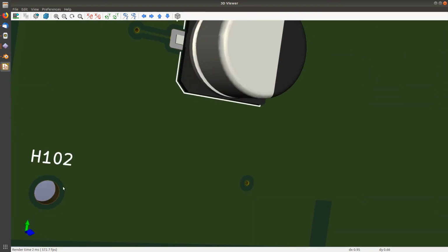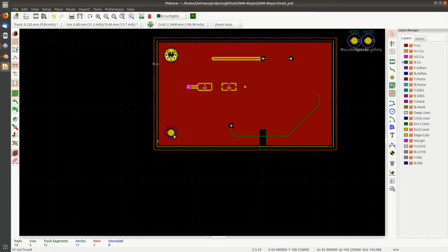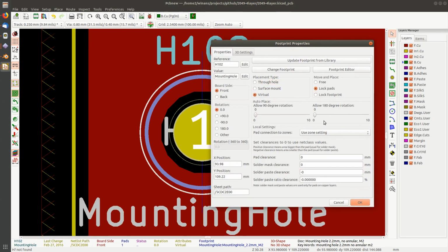I did not go and specify the clearances like I did when we first did one. I'll quickly do that just for fun. Remember, if I click here, I'm clicking a pad. If I go over here, I got the whole part. Maybe I want to lock it. Maybe I don't. Whatever. I want a 2, maybe a 1.85. Let's say the guy says he's got a 0.1 registration accuracy with his solder mask. Well, I'm going to go down to 1.5 for my clearance, right? Because I'm going to have 2 millimeters away from the edge of the pad for the copper and 1.85 for the solder mask, which gives me 0.15 clearance